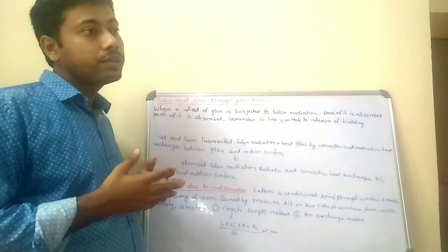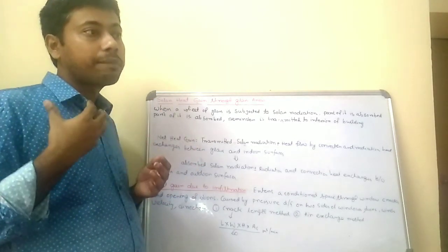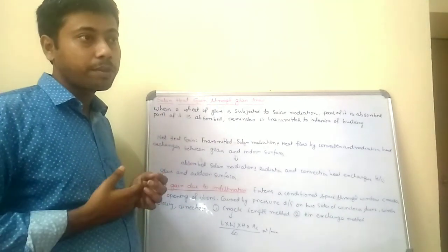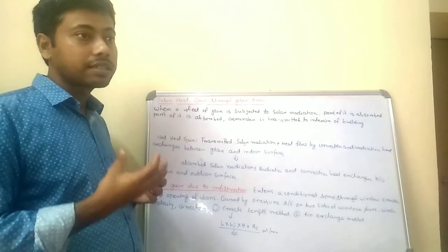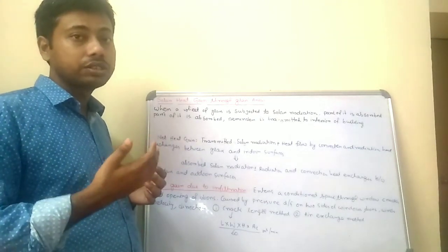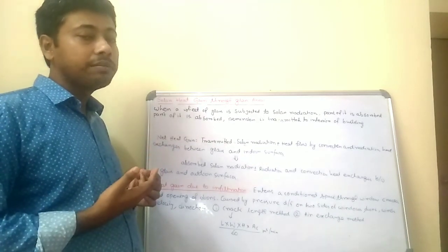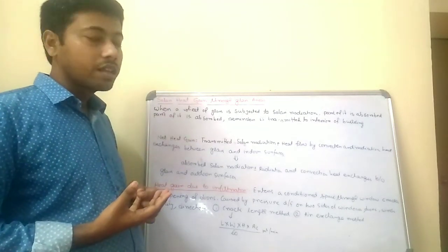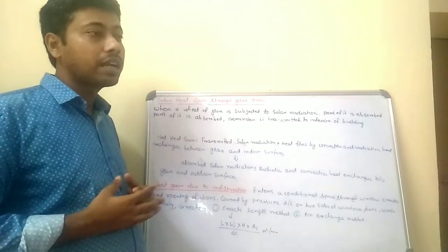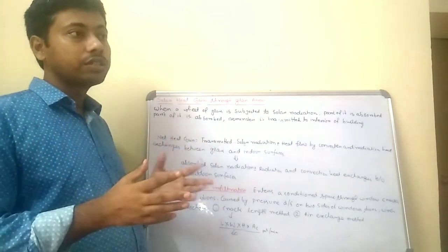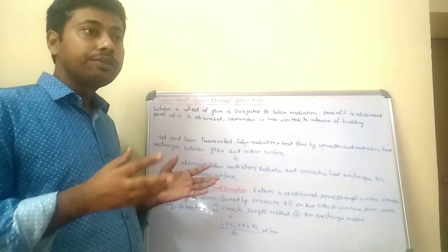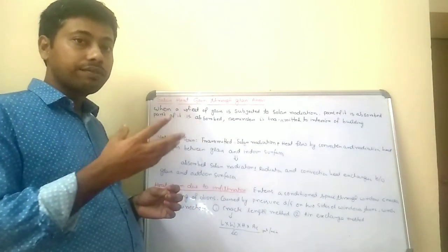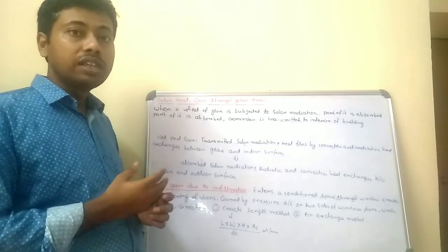But when the temperature increases, the heat absorbing capacity of the glass fibers is limited. So obviously they will release some part of it when they go beyond the limit. Beyond that limit, the maximum amount of heat will be rejected into the room. So the maximum amount of heat enters the room, and due to this the major load will be applied onto the cooling apparatus.